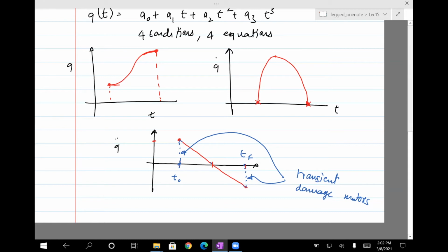And then if you do that, you'll see that your position, velocity, and acceleration will all look smooth, no transients, but your third derivative, which is called jerk, is going to have a transient. So if you want to avoid that, then you need to keep increasing the polynomial order. And so that is something which keeps going, and you just don't want to keep ramping up the order. So what you eventually end up doing is you stick to some order. Typically fifth is good enough, and then you don't go to seventh and ninth, and you just live with fifth. Okay.